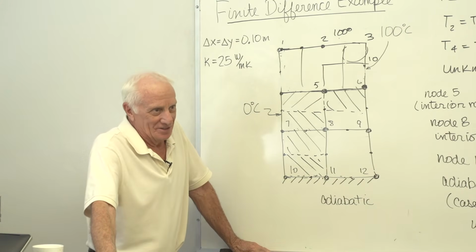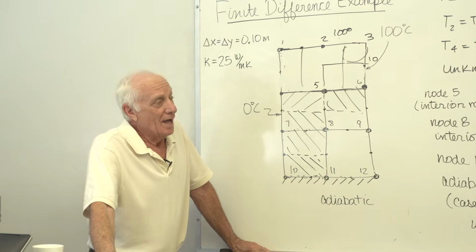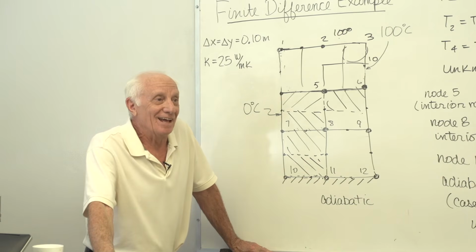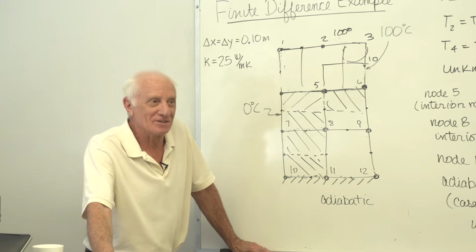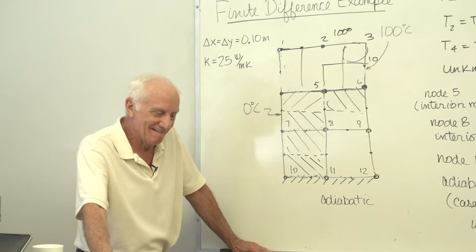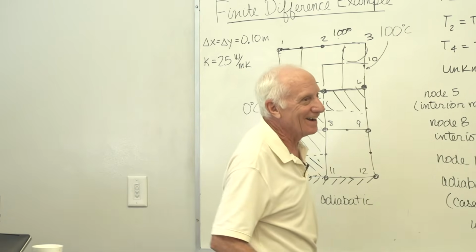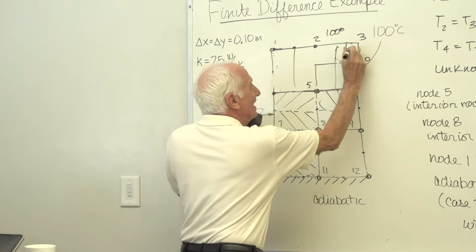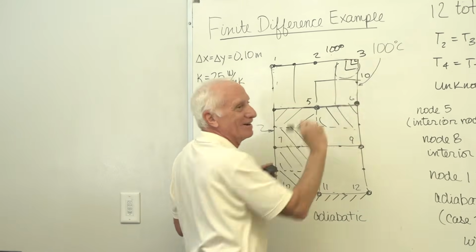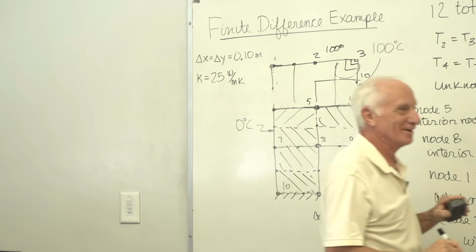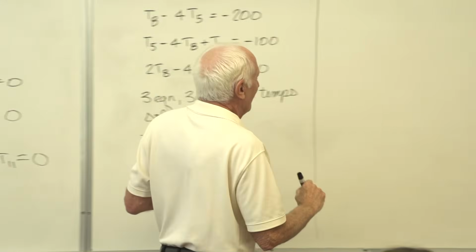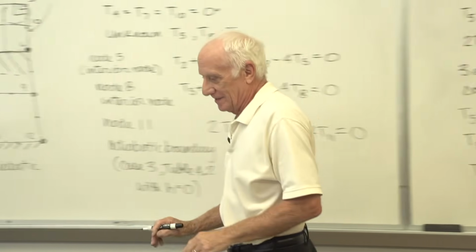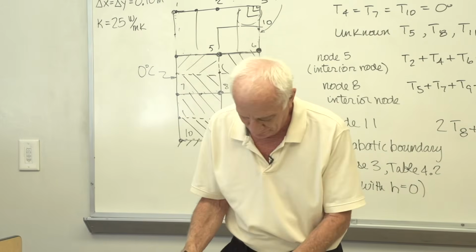You know there are errors built into this. But guess what? As you keep reducing the grid size, they go away. The errors get smaller and smaller. The problem areas get smaller and smaller. They only happen at the corner. Now you're missing that much, now that much, now that much. At what cost? More computing time. Okay. That ends our chapter on 2D heat conduction.